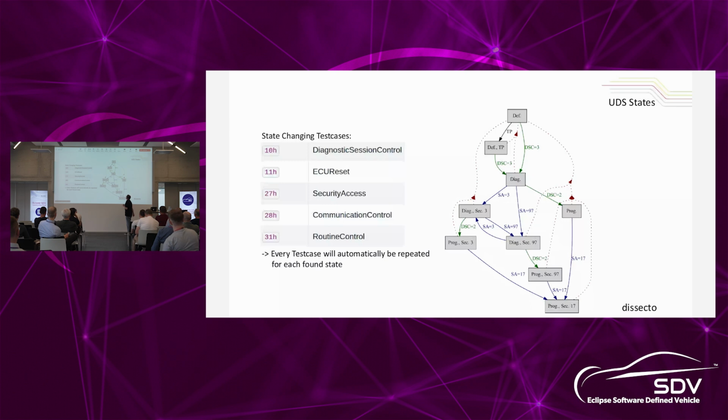The scan takes a minute. So here you see an example tree of the ECU, 5 points if you can guess which OEM this is. And here we see the different sessions. We always start in the default session, then we have an extended diagnostic session, and then we have a programming session. That's the normal standardized thing. And then we have also different security access levels. And to find out what the ECU really supports, we need to make a service scan.